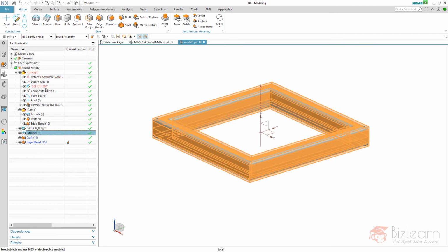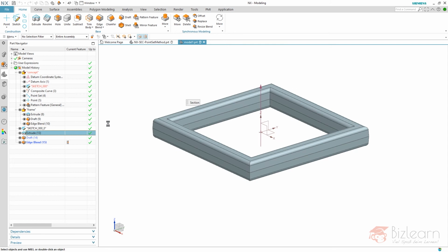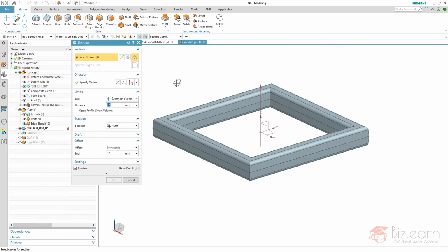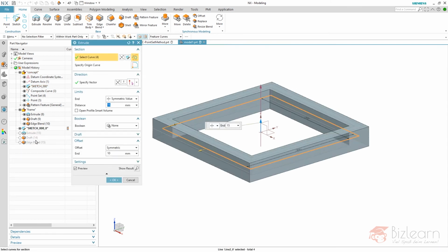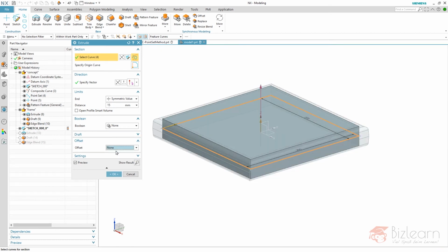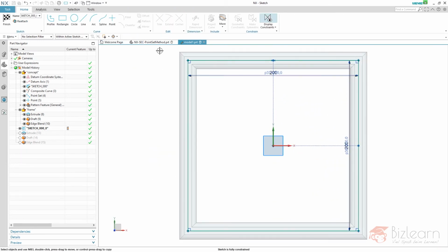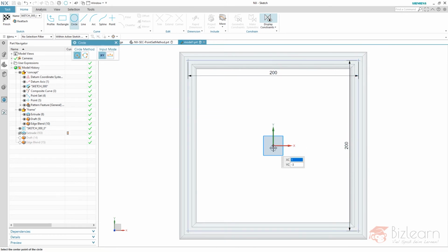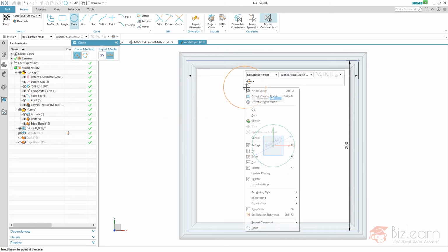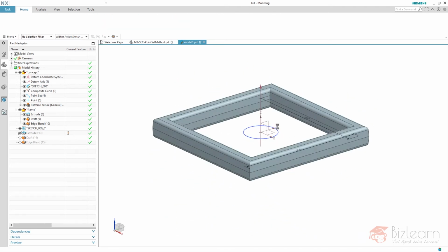You can see the extrude is still referenced to this sketch. Okay, that's a mistake. So I'm going to double click this, deselect, and select my new sketch here. And that's all I have to do. It's not symmetric, it's none. The value here is a little bit bigger, 25. And I'm going to replace my curve by something round maybe. It could be rectangular, but I'll start with a round boss. Let's make it 50. And finish this one.